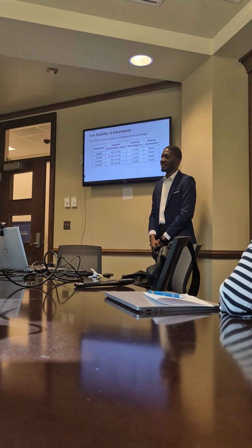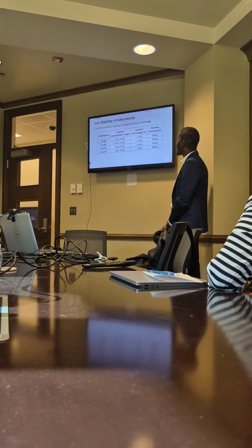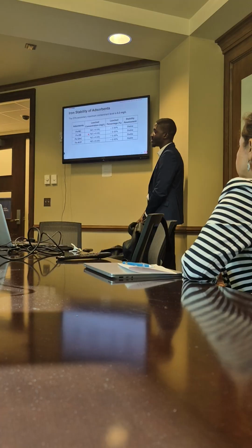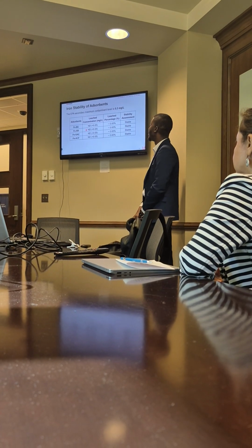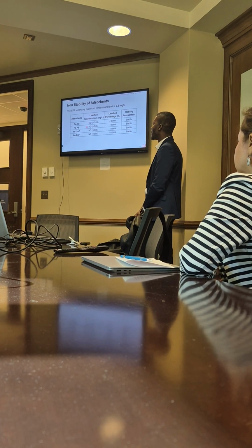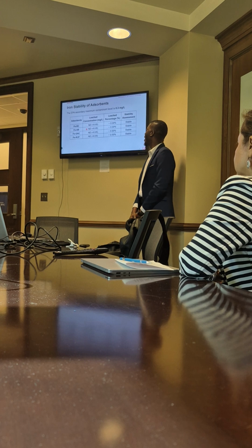And for the iron leaching test, the EPA recommends having a maximum iron contaminant in water capped at 0.3 milligram per liter. And as you can see, with all our adsorbents, we didn't detect any form of leaching. So our adsorbents are very, very stable in solution.